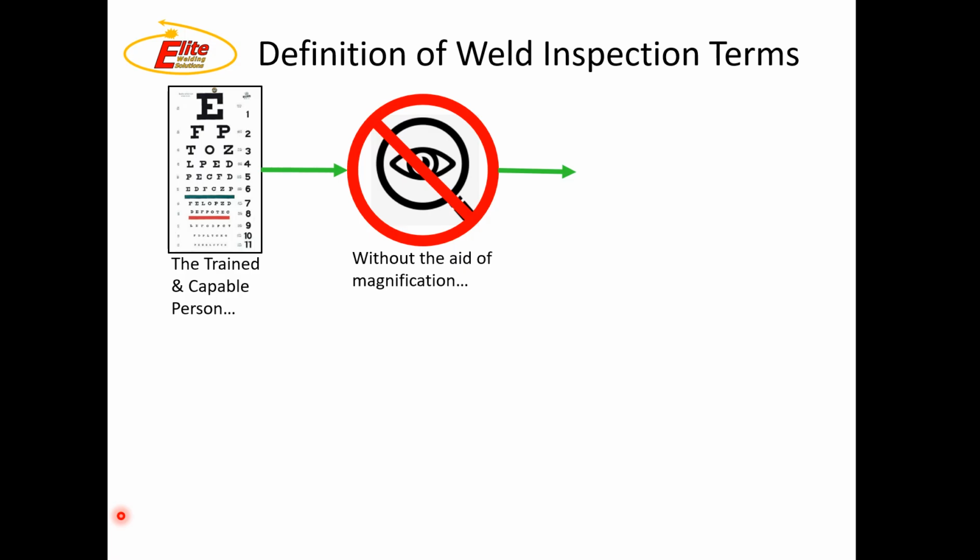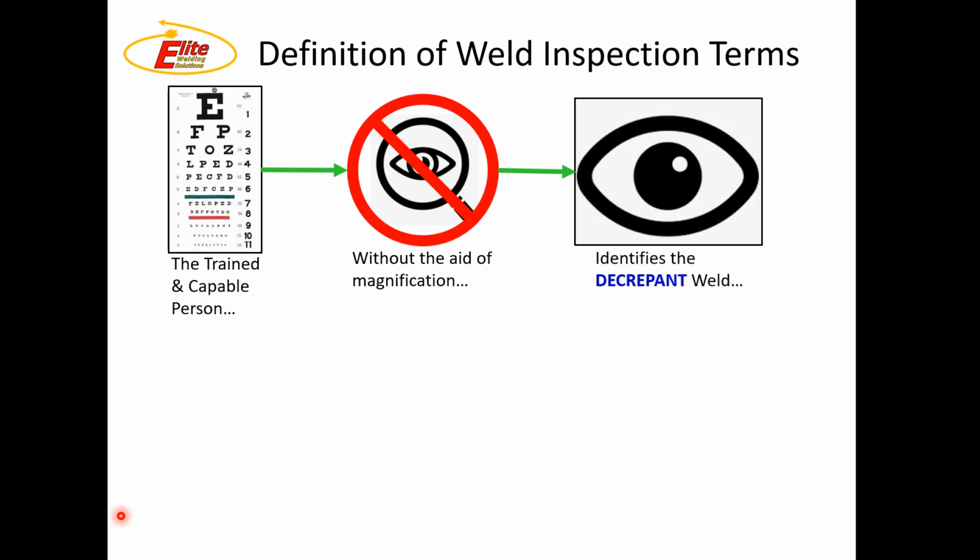That's why we'll sometimes have multiple inspection stations, inspection points even, where we define whether or not this is good or bad, and should it carry on in the process or should we stop the whole line. You shouldn't have to get on top of a weld. You should be able to inspect the weld from pretty much arm's length. If you held your hand out in front of you and stuck your thumb out, you should be able to inspect something from that far away. Going back to your eyesight, that's the important aspect of it. So, you've looked at it. Whoops, it's a discrepant weld.